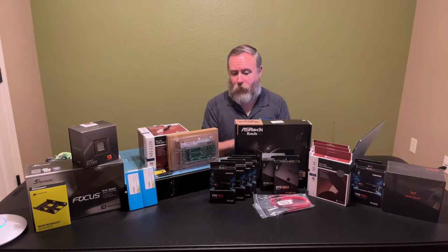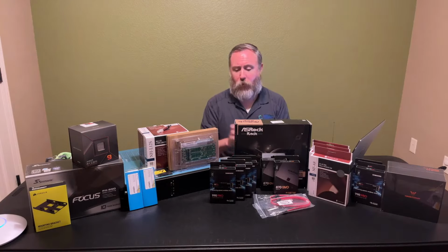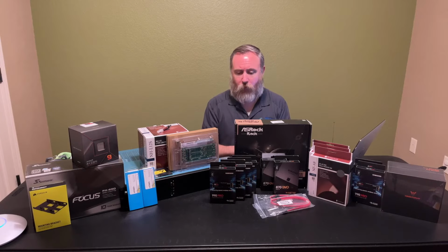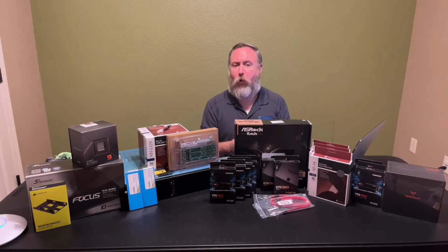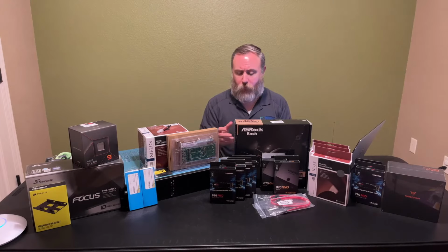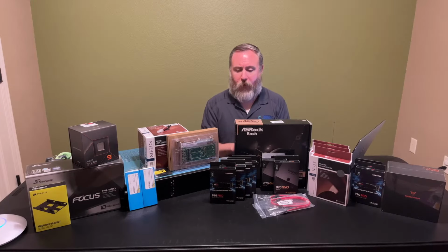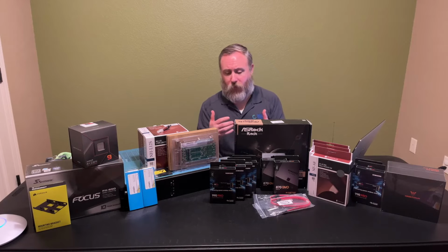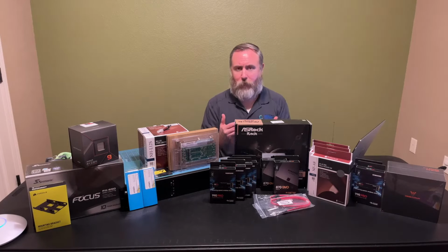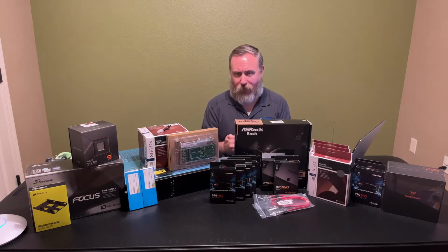If you might remember, there was a known issue with the Samsung 990 series with certain particular firmware versions where the drives would wear out so prematurely. It was really an algorithm issue, a bug in the firmware. The drive thought it was full, not really full in the sense of capacity, but that the maximum number of writes allowed for that drive in its lifetime had been reached. It would not allow any more data to be written to it.